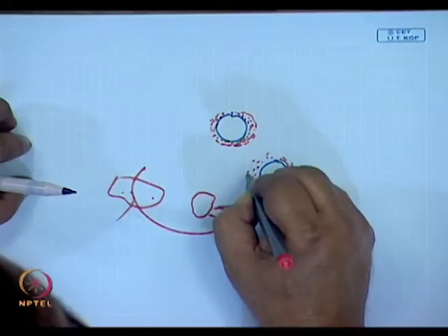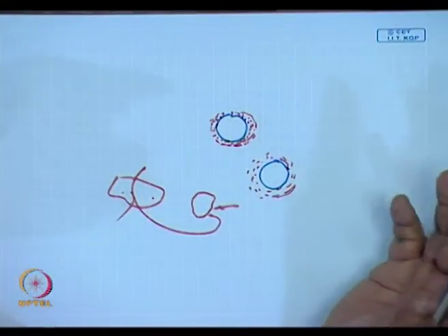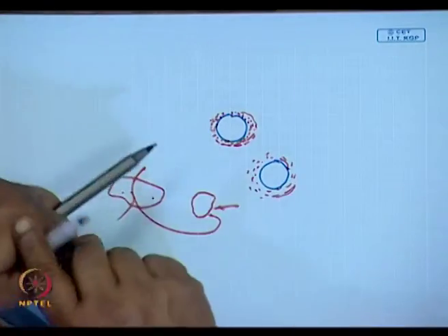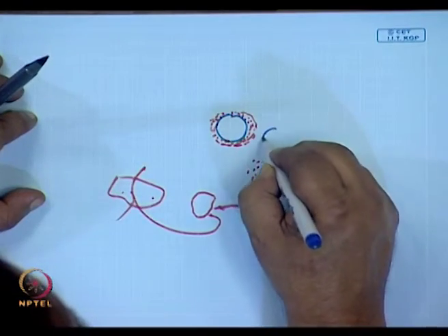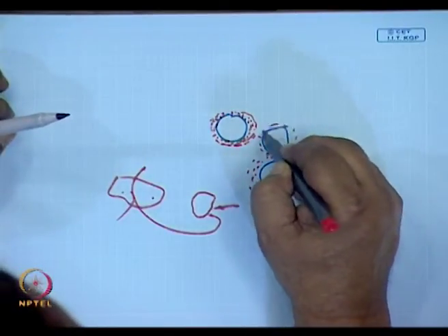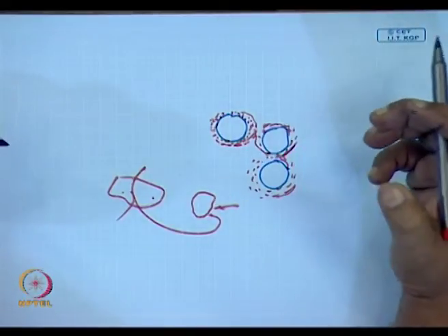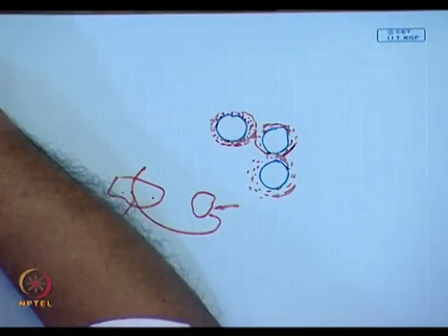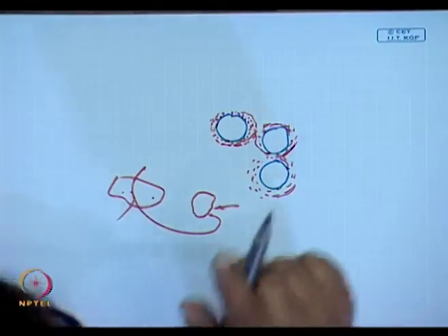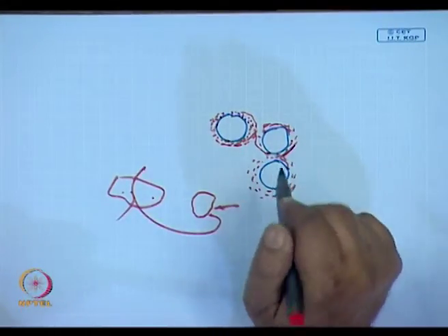No further grinding occurs over here, and further grinding stops. Let me assume 3 over here. So, all of these are coated with this fractured ceramic powder. They are sticking onto the balls. No further grinding occurs. This is a major disadvantage of dry ball milling.